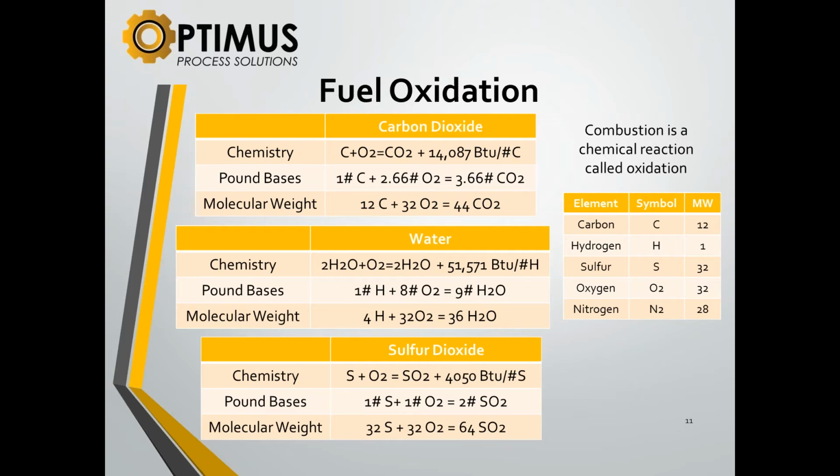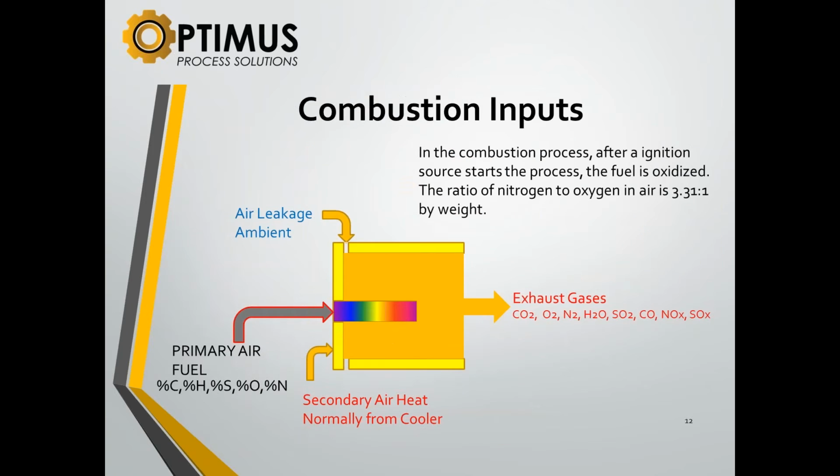Which will do a lot of nothing. A lot of people, when a coal truck comes, they wait until it rains before they deliver. So if the moisture content is high, it's very costly in this process. And you have to dry it, maybe in your grinding system. So you're telling me a very practical thing to do right now is to know the chemical composition of my fuel. Yes. Okay.